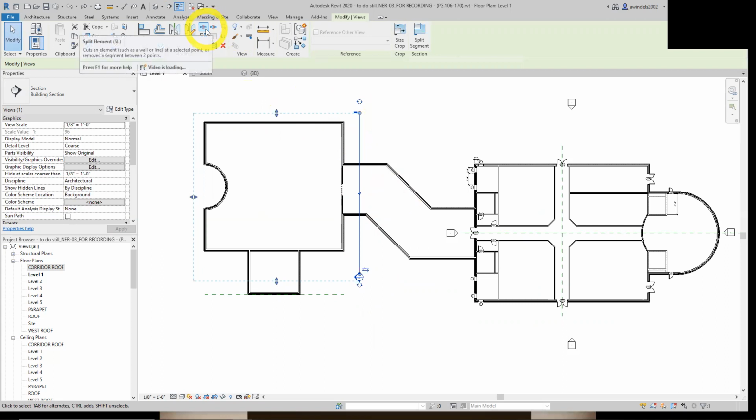I want to show you one more edit. You can cut it like a zigzag pattern across a building as well. That's a little more advanced, but maybe you have a really particular part of the building you want to cut. So section view looks in the direction that the arrow's on, and it cuts into the building.